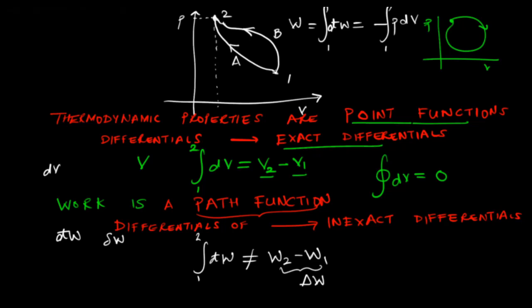So what we say is that we can use this notation that the work done during the process is W12. That means the process that takes the system from state 1 to 2. But note that there might be many different processes by which you can go from state 1 to state 2, for example, shown in this plot. So we have seen in the previous lecture that if we have a quasi-equilibrium process where we change the volume of a gas, then the differential work is given by